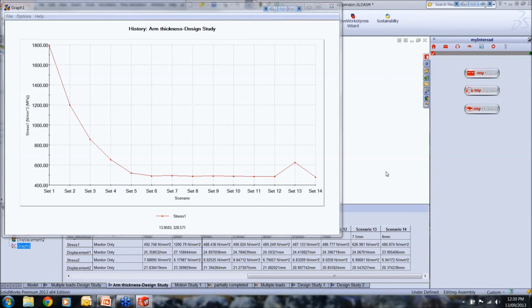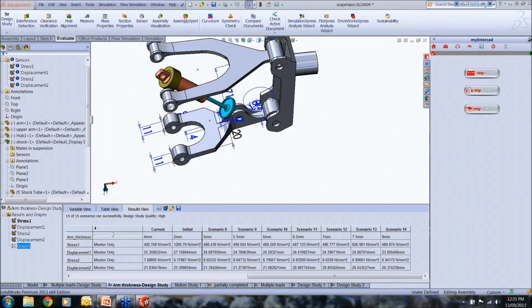Okay? So what we had up to this point is showing how to first create a study, specify some parameter, which could be loading or geometrical factors, then specify a range of these parameters in our design study, and then say what is important as an output to trace, could be stress, displacement, and so on, and run the case study.